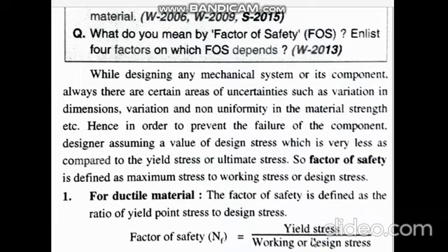If it is of length 100 mm, however much load comes, that 100 mm should remain 100 mm. When the load is removed, it should come back to 100 mm, and should not be 105 mm or 110 mm. If it has become 105 mm or 110 mm, it has yielded. That yielding should not take place.